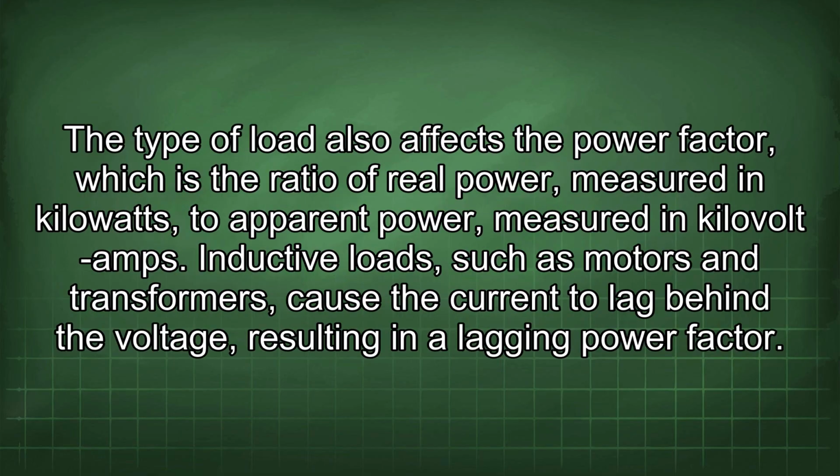The type of load also affects the power factor, which is the ratio of real power, measured in kilowatts, to apparent power, measured in kilovolt amps. Inductive loads, such as motors and transformers, cause the current to lag behind the voltage, resulting in a lagging power factor.